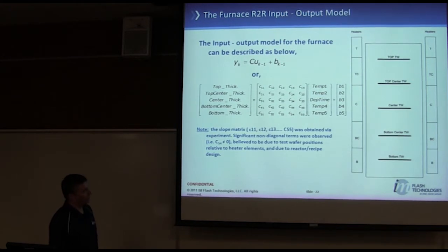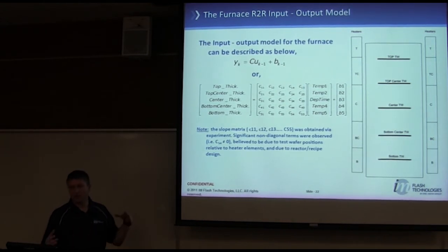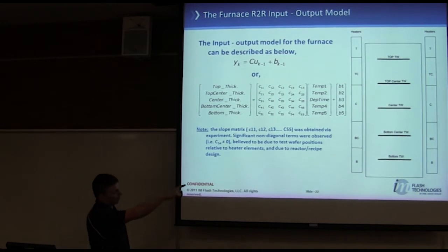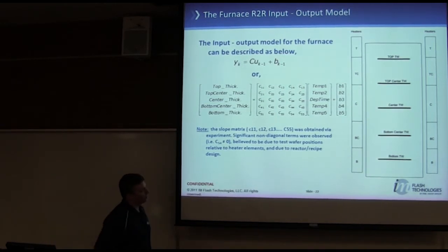But anyway, okay, so this is another example. Darren just shared one from dry etch. This is an example from diffusion. Basically, in diffusion, we put a bunch of wafers in a big furnace, and we flow gases in the furnace, and we deposit some type of a film on the wafers. And so this over here just shows what a diffusion furnace would look like.